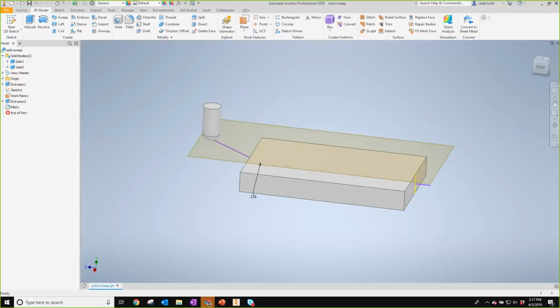One thing I thought was interesting, and this was just a note that I read in the help, it said, if the sweep fails to compute, try removing fillets. In some cases, it may help to add fillets. So I guess good luck. Fillets will work one way or the other. But what I'm going to do is I'm just going to go through and sweep this along.